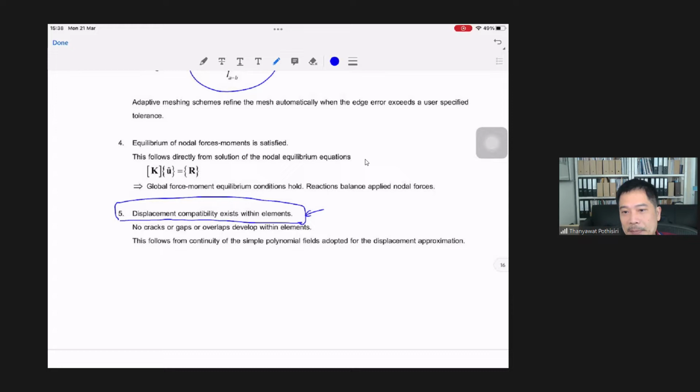Because as we mentioned before, in modifying from the differential form of the equilibrium equation to an integral form, or a weak form, you change the continuity requirement on certain functions. So even though you allow stress and strain jumps to exist, no displacement jumps are allowed. That means if there are no displacement jumps, then displacement must be continuous.